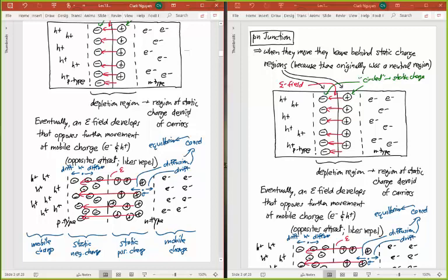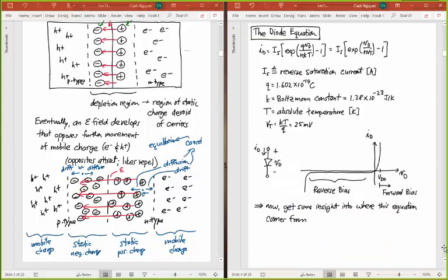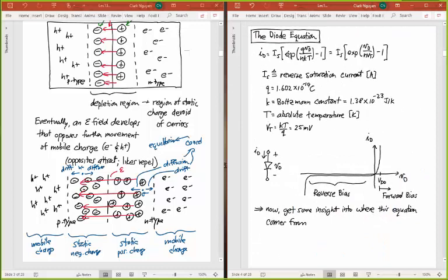And like I said, a p-n junction is a diode. And so let's review what we're going after. So we now know the physical structure of this. We want to get at this. Remember our diode? So we talked about the diode, a real diode. We talked about the fact that it has this IV characteristic. This is the current. That's the voltage drop across this diode. When my voltage drop across the diode is negative, I essentially have very little current. There's a little bit of current flowing here, and that's sort of modeled by this I sub s. We're going to come up with an expression for that I sub s in terms of physical parameters shortly.